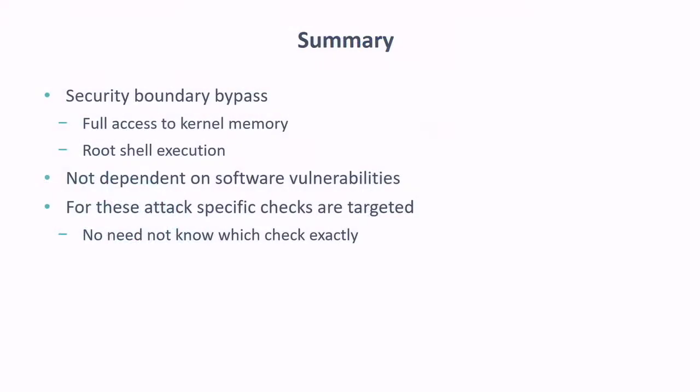It's important to realize that this kind of attack focuses on a specific point in time, on targets where there is a check, and you want to shoot at it in order to see if you can actually change that behavior. This has been a very widely used attack, also during secure boot, also in academia. If you have a check at some point, you might want to duplicate it, so that I need to shoot at 2 checks. So it is more difficult.